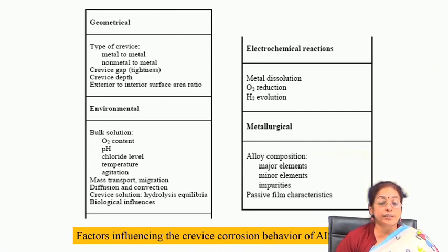You can also get rid of crevice corrosion by proper choice of material. As I mentioned, if the film which forms on the surface protects the surface to a large extent, then it can minimize the tendency of crevice attack. For example, take mild steel, 304 stainless steel and 316 stainless steel.